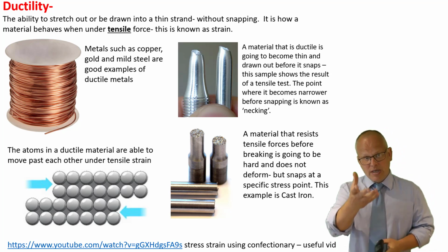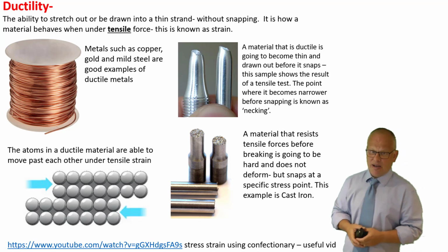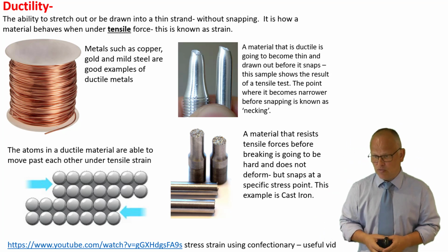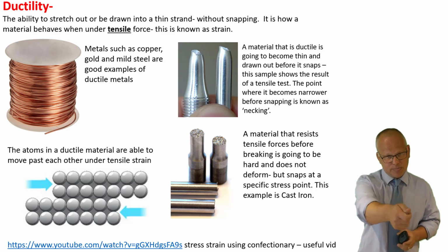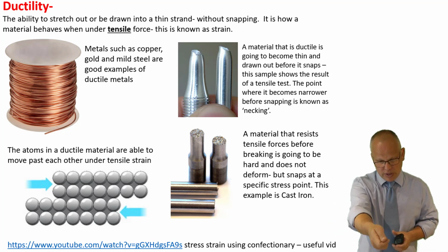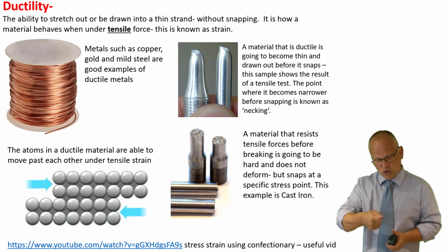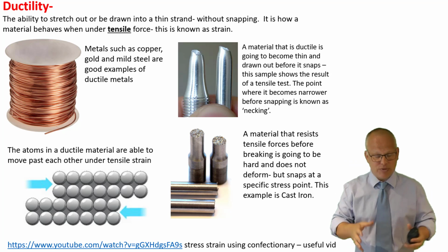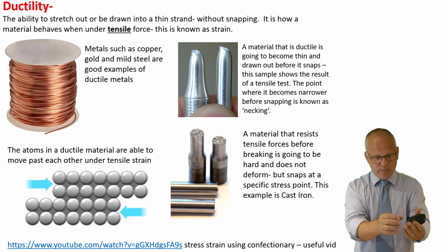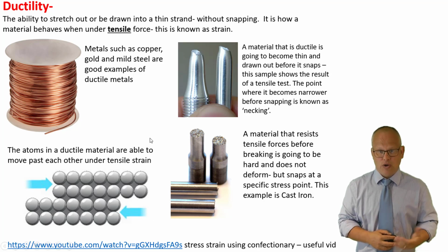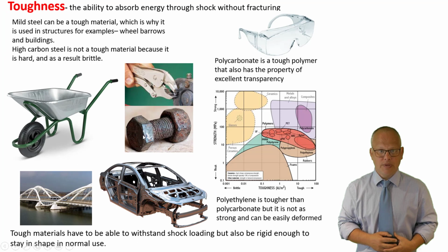It can't be stretched. Ductility is important for making things like wire. Lots of metals can be pulled into wires or rolled into wires, but it's the ability to pull it through, and you can do it by hand with things like copper and silver. You can pull it through a tiny little hole with some draw tongs and actually reduce the diameter but increase the length at the same time, as that volume of material is changed into a different shape. Okay, so that's ductility. Something is ductile. Copper is a great example of that.